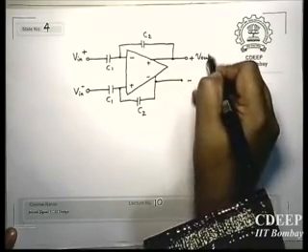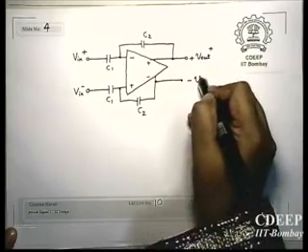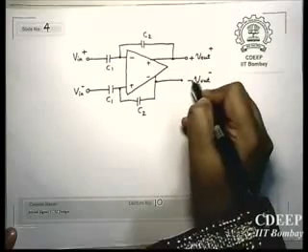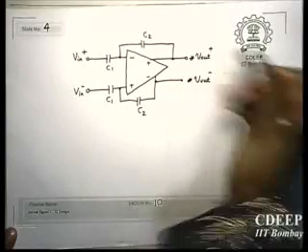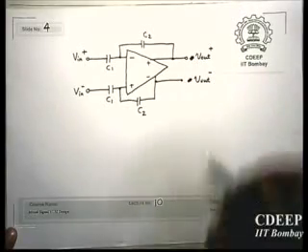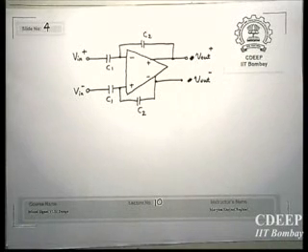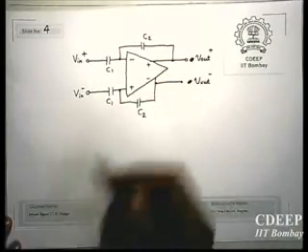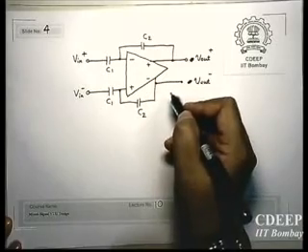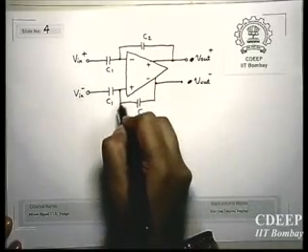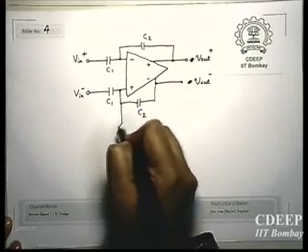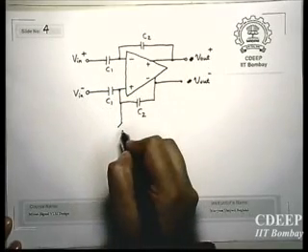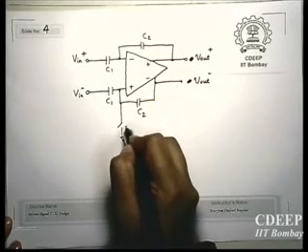This is Vout plus, Vout minus. And then we sample it either in phi 1 or phi 2. There is a small comment here also, I will explain. Let's first draw the entire schematic. Then we go with CA, which was playing the role of a resistance parallel to C1. So phi 2.